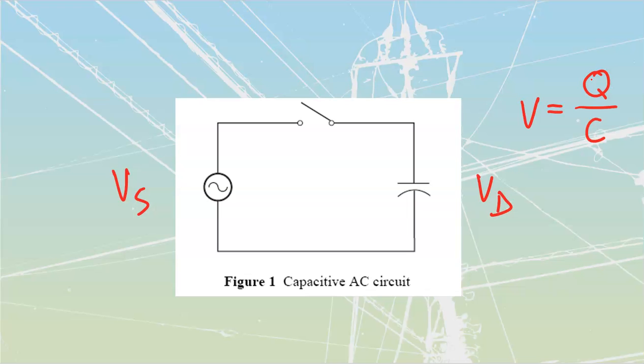So anytime that my voltage source is at a peak, I must also have a peak of coulombs of charge in order to match that, so that I can have that opposition to voltage, or that dropping of our voltage across there. Anytime that my voltage is dropping, I'm also going to be releasing electrons off of the plates to drop my V, because the only way for me to drop the V is to be dropping the total coulombs of charge that I'm going to have on it.